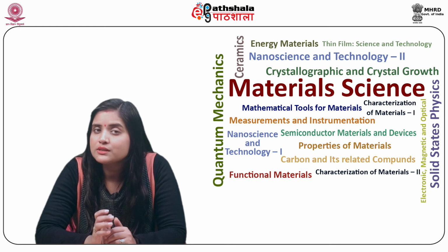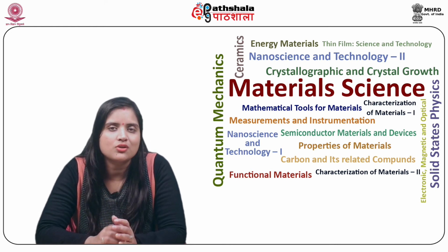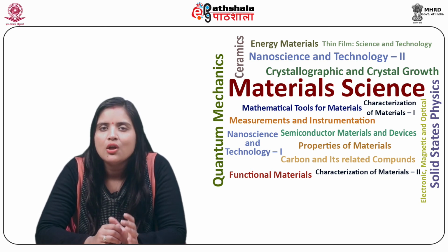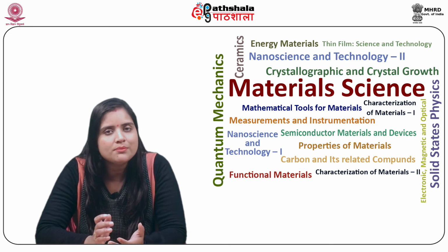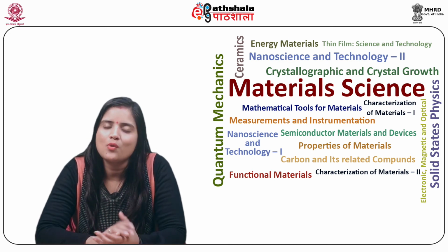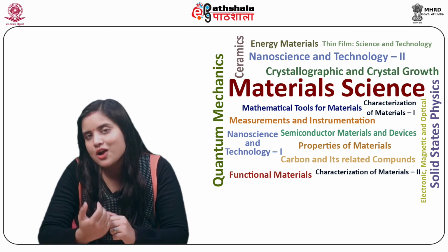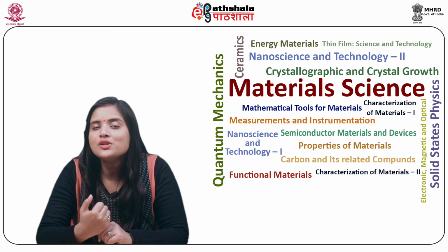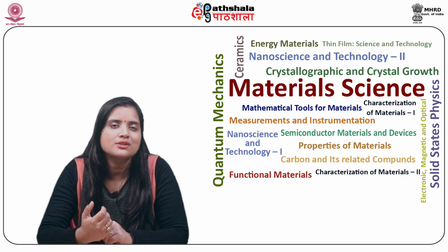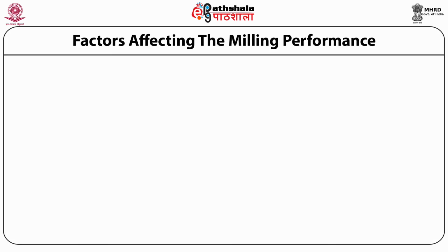Aside from these concerns, other drawbacks of ball milling include long processing times, no control over particle morphology, possibilities of particle agglomeration, residual stress in the crystallized phases, etc.